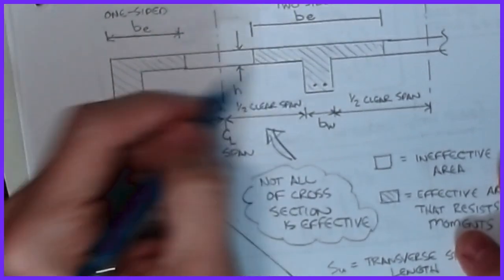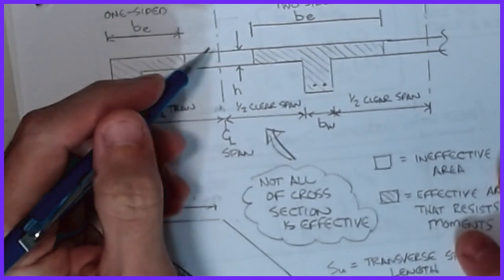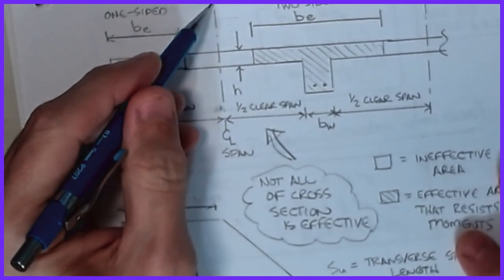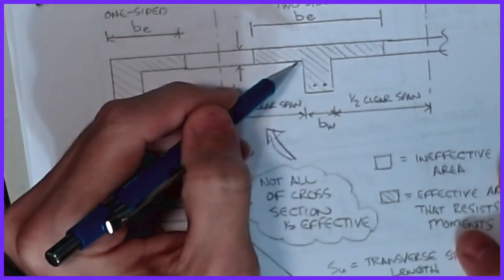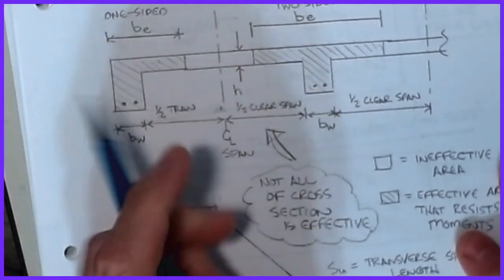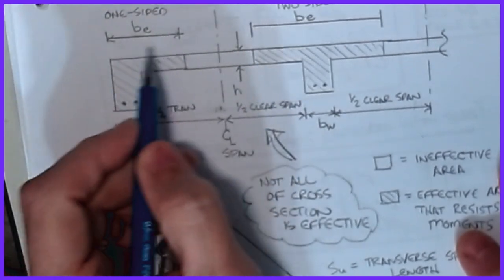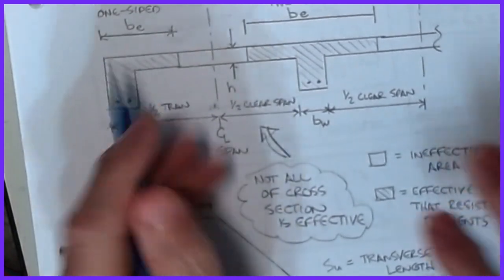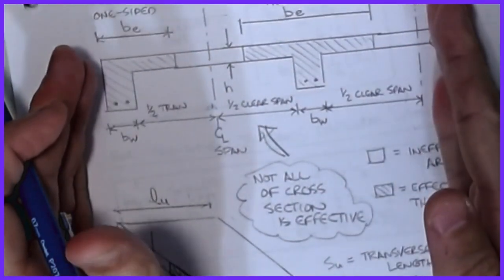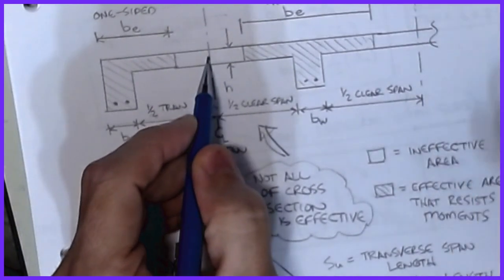If these two are very, very far apart, it would seem logical that one of the things we could do is locate the center line of the open span and just give half of it to either side. Now, if these are very, very close together, then that's a pretty reasonable estimate, depending on what these effective dimensions are for the one-sided and the two-sided. But if I start spreading these things out so that it gets a lot further apart, now there's a region out in the middle that may or may not be doing its share of the work.